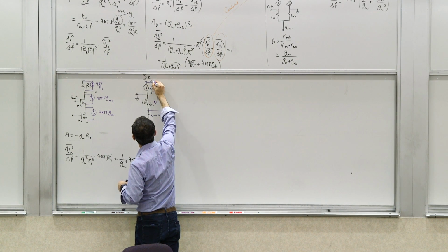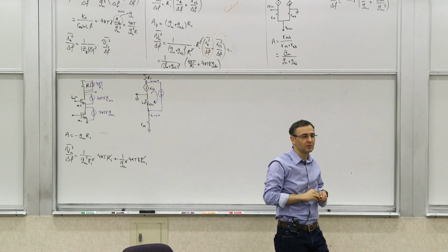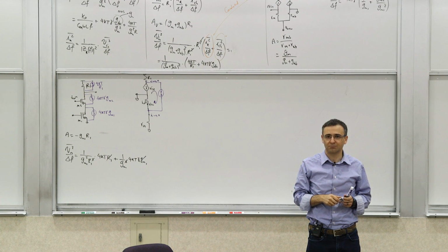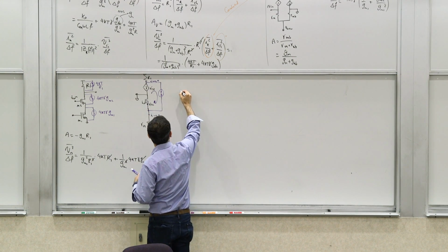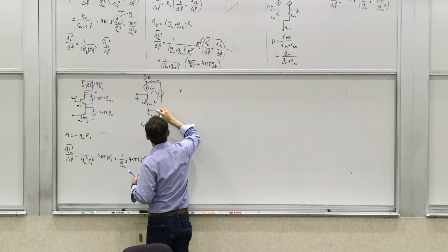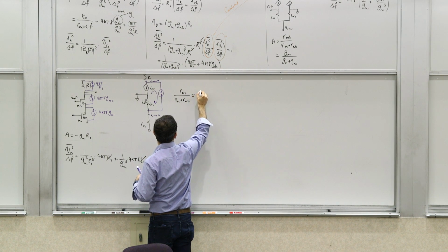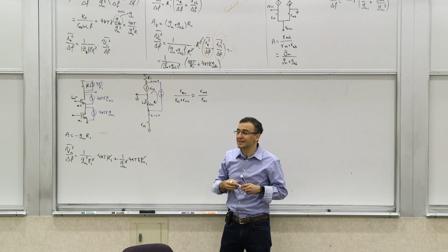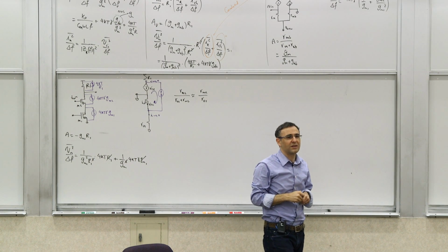How small is determined by the ratio of RM and RO, usually a small ratio. Exactly, the current that actually goes here is RM2 divided by RO1 plus RM2, which is roughly RM2 over RO1. That's the fraction of this current that ends up at the output, a very small fraction.